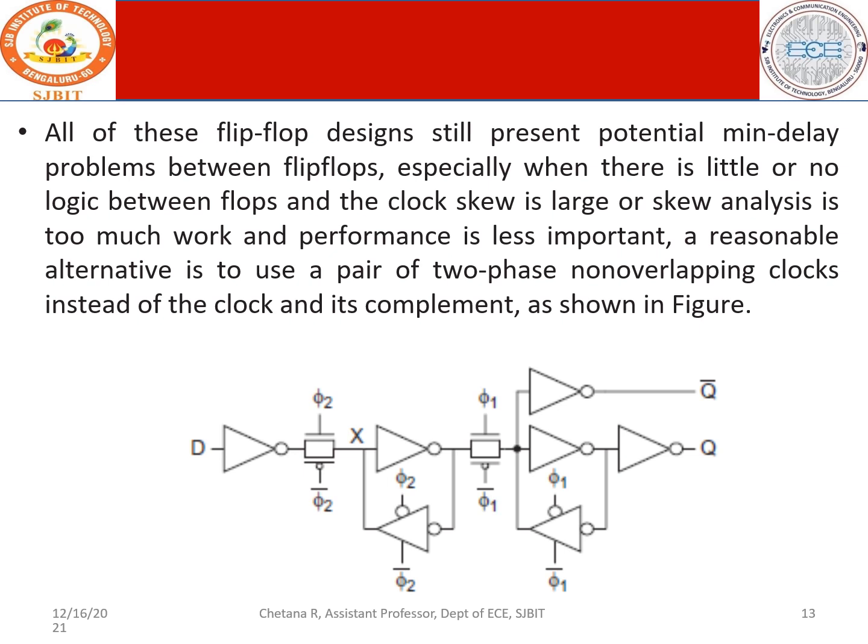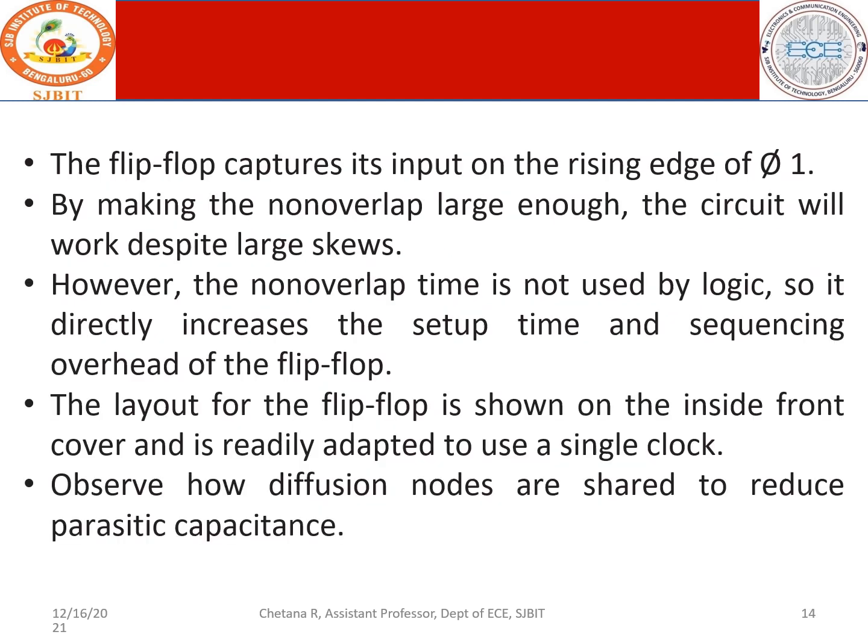So instead of using clock and its complement, we will use non-overlapping clocks. So when one of the clock pulses is high, the other clock pulse is low. They'll never overlap, and that gives you a better design as claimed by the author. Better design in terms of clock skew analysis, work and performance.